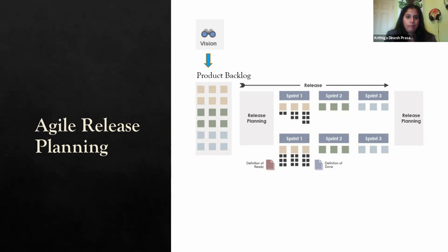From the DO-178 perspective, now we got the system requirements, we got the system aspects of software requirements, and then we determine the criticality level of the software, and we need to kick off the software planning process, and then we kick off the project, and then we kick off the release planning. And in the release planning, we add epics, very high level epics of what is needed for my immediate milestone. I need to do the software planning process for agile, and in any organization, we need to have an overall plan of how things need to be done.